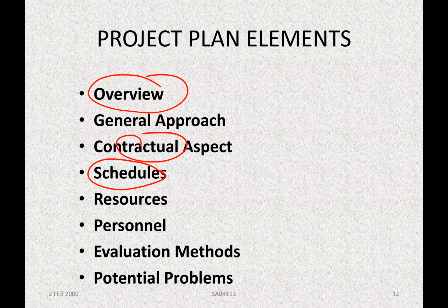Schedule is basically the timing, when you want to start something, when you want to end something, what are the resources. Resources will reflect the timing as well. Let's say, for instance, if you want to do excavation, if you do excavation manually using manual labor, of course it will take longer. If you replace those manual labor by excavator, it will be much faster. But if you bring in not only one excavator, two excavator, three excavator, for sure you can cut down on the number of duration of the activities. So you see, resources basically interrelated with the duration of the activity.